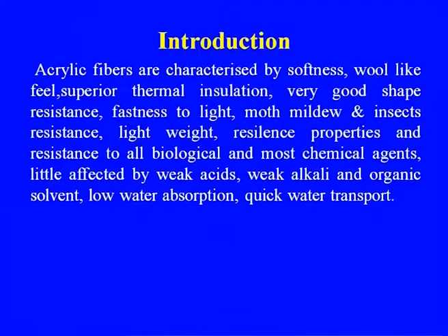And the other properties are lightweight, resilience, resistance to all biological and most chemical agents, little effect from weak acids, weak alkali and organic solvents, low water absorption, and quick water transport, meaning drying is much faster in the case of acrylic fiber. This is the reason why washing of material made from acrylic fiber is also easier, because the water drainage is fast.